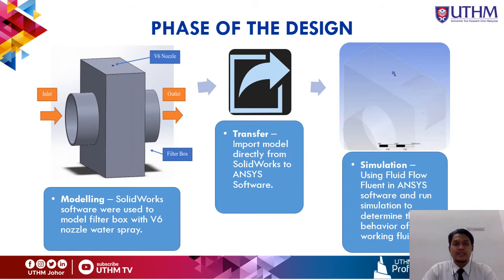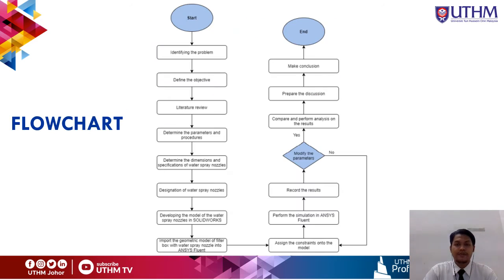Next is the phase of the design. First, about modeling, as you can see at the picture there. Second is transfer, which is import model directly from SolidWorks to ANSYS software. And third, simulation, using fluid flow Fluent in ANSYS software and run simulation to determine the behavior of working fluid.